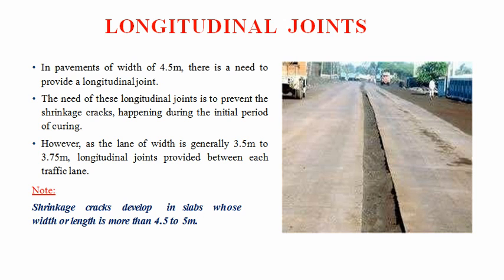However, when the lane width is generally within 3.5 meters to 3.75 meters, then the longitudinal joints are provided between each traffic lane. Here, we should note that shrinkage cracks develop in slabs whose width or length is more than 4.5 to 5 meters.